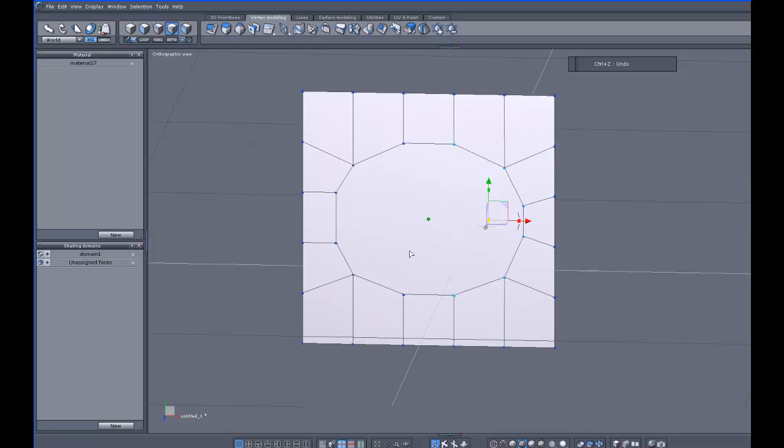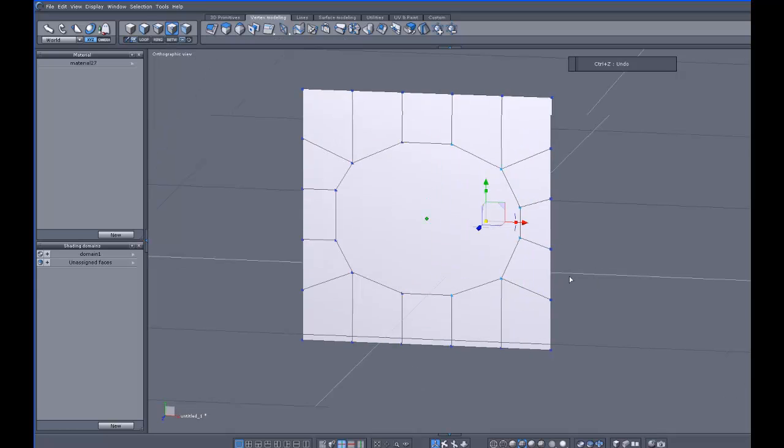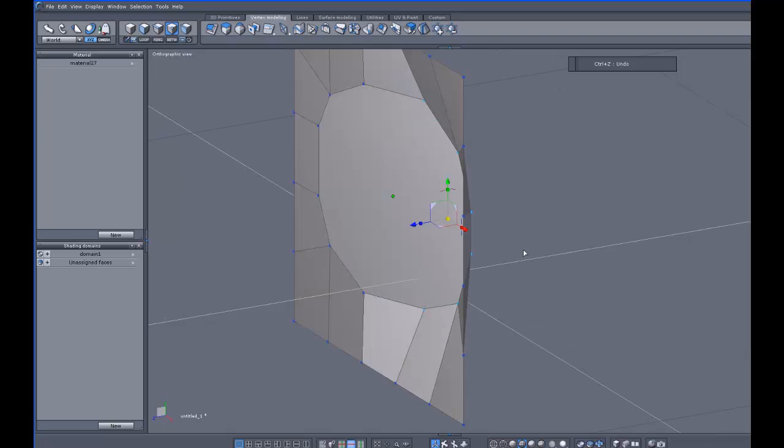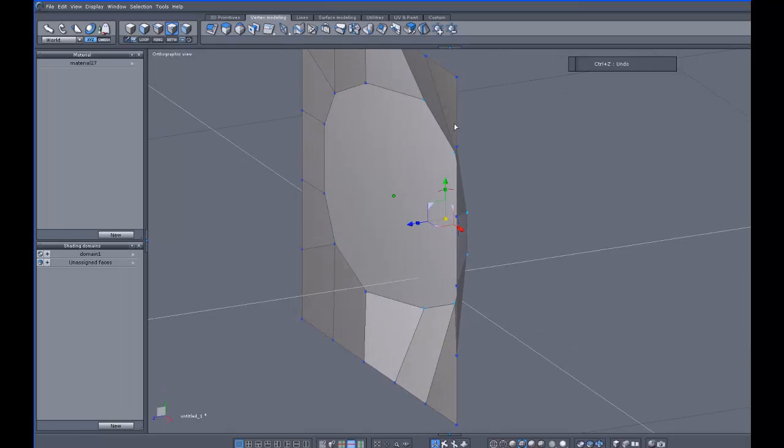Also have an option to offset what's selected. So if I was to select some points right here, then I would snap to the reference at, let's say 50% would be here, then let's say 100% would be here. Now when I push it back, you can see I still got my edge in the front there. It's kind of right here. It could cause a problem.